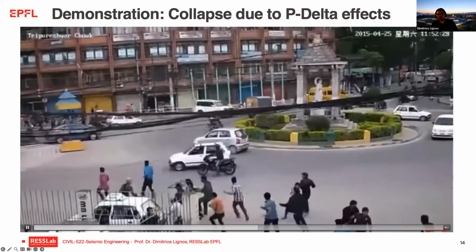Now, in the examples I showed you earlier, you saw that when I have lateral deformations because of the seismic loading, there could be a possibility of having damage in the ends of the member. And that would mean that once my frame reaches a critical displacement here, it will essentially enter into the nonlinear regime by hitting a strength equal to Vy.